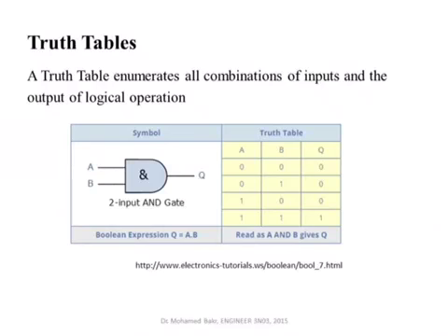We have one of the gates. This is the AND gate. We'll see this one very often later in the course. We have here two inputs. You can look at them as two logic variables, or we can look at them as two signals. These two signals can be either true, meaning logic 1 or 5 volts, or false, meaning logic 0 or 0 volts, or depending on whatever the voltage may be. But the output Q from this AND gate will be true only if these two are true.